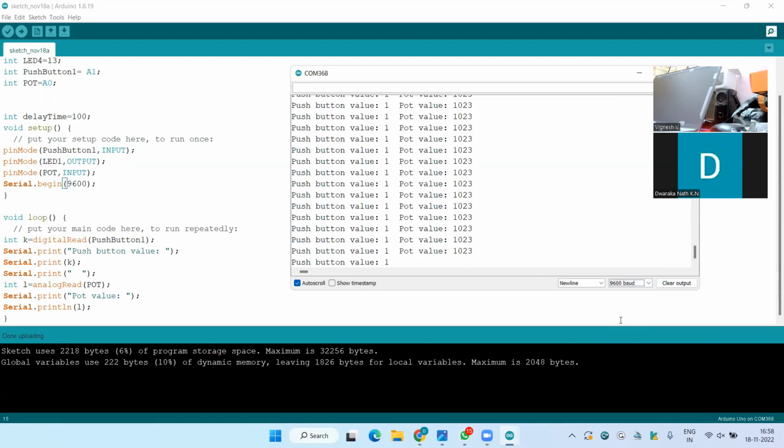So you have learned regarding the potentiometer. Now we will do something. 1023 is 5 volts. So we will tell this microcontroller I am applying 5 volts. So how can you say this one? So assume 5 volts is 1024, 0 means 1. Okay. So we will make a scale equation and we will write a small code here.